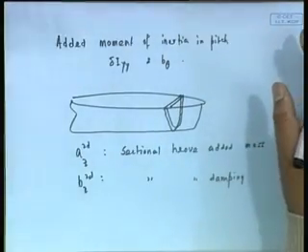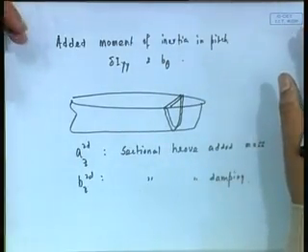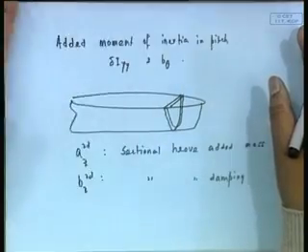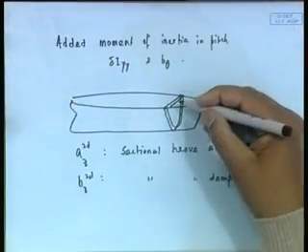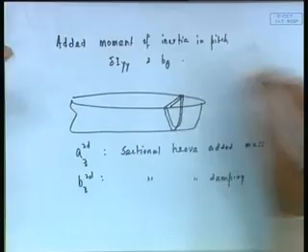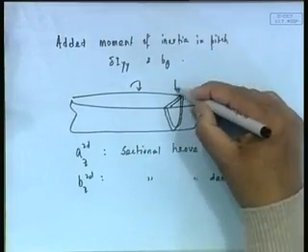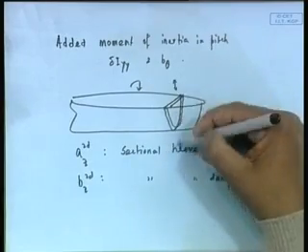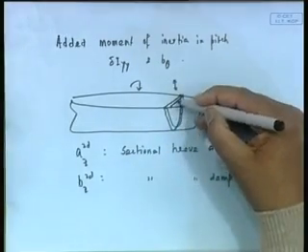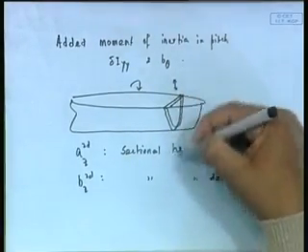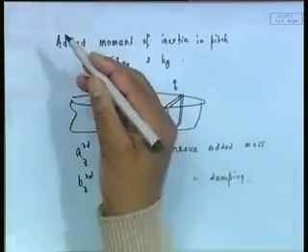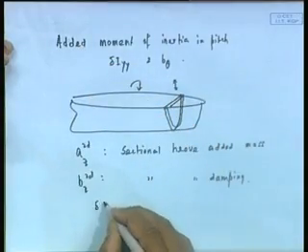Remember in the previous class we mentioned strip theory, that the ship was made in strips and you are oscillating. Now, here heave and pitch are so correlated that if I were oscillating this way, it basically means sections are oscillating this way. So, as far as pitch is concerned, this has a sectional added mass, and what is my pitch moment of inertia, that is delta Iyy.